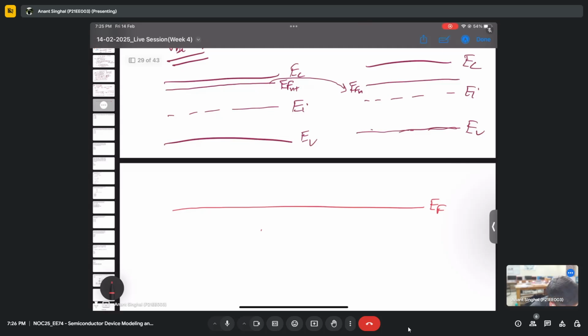So what I said is the Fermi level will align, right? So the flow of electron is from higher Fermi to lower Fermi. So let's say this is EC. This is, let's say, EF1 and EF2 are aligned now. This is EV1 and this is EI. So this is what we know as phi 1, or Q phi 1, let's say.